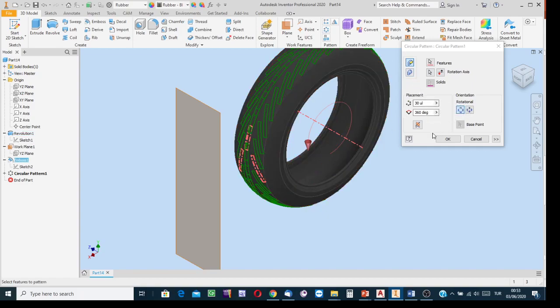For the array copy process, the distribution angle of the members of the family is 360. Then clicking on the axis indication button, I indicated the edge of the tire, saying that its longitudinal axis is the axis of distribution. And then created the copies, saying just okay.